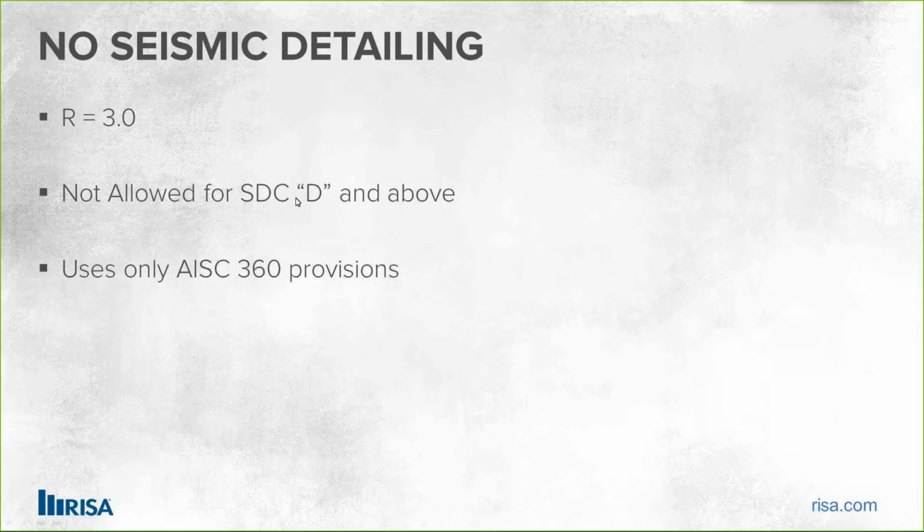However, a limitation here is that these types of systems are not allowed for seismic design category D and above. And so anything with any decent amount of seismic in the structure, you're not going to be able to get away with this R equals 3. The code does not allow it. And so in that case, you have to start delving into the seismic moment connections.